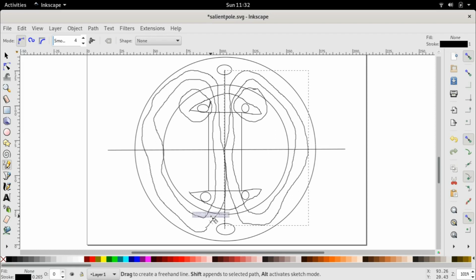As already said, because the stator and the rotor are high permeability paths, with a permeability almost 1000 times higher than that of air, quite obviously the reluctance of this entire flux path can be approximated to just the reluctance of the air gap, right? Because these flux paths, even though they are longer, have 1000 times higher permeability. So therefore, really speaking, the entire flux path is determined by these air gaps here.